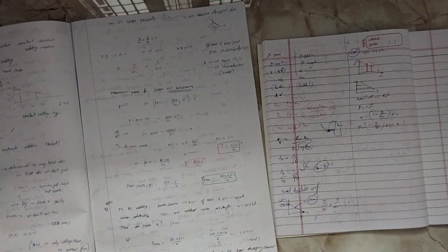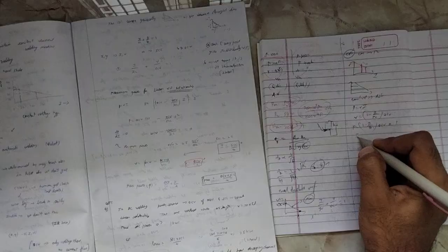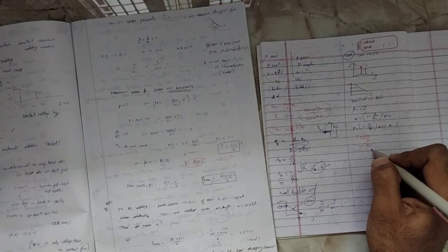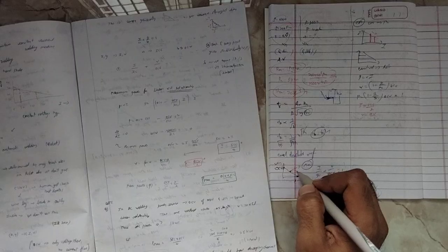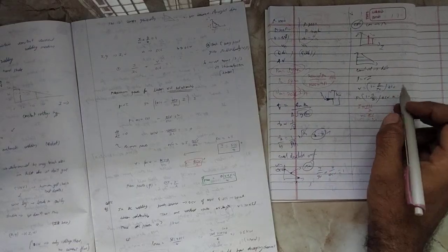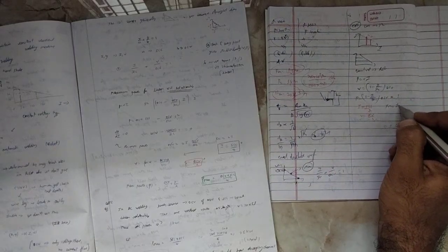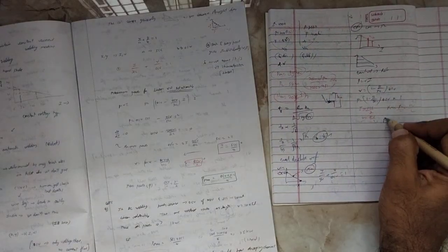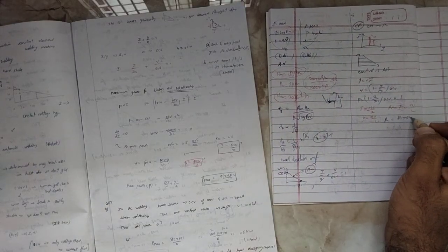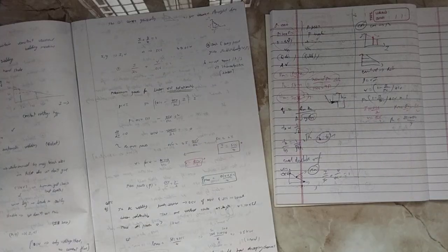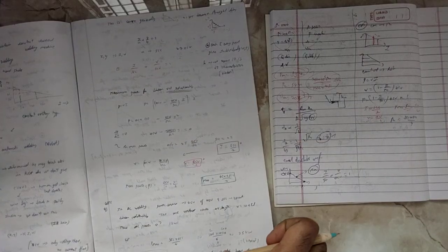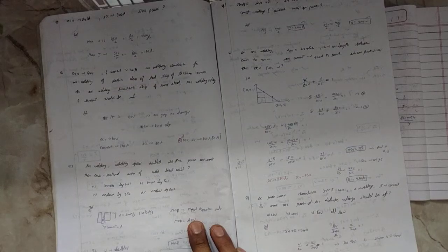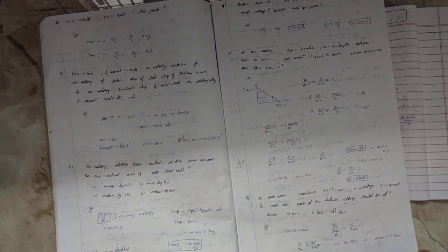So what is the value? I equals SCC divided by 2 and V equals OCV divided by 2. So at this midpoint we get the maximum. Power maximum equals SCC divided by 2 into OCV divided by 2, so power maximum equals SCC into OCV divided by 4. So these are the extra questions there.